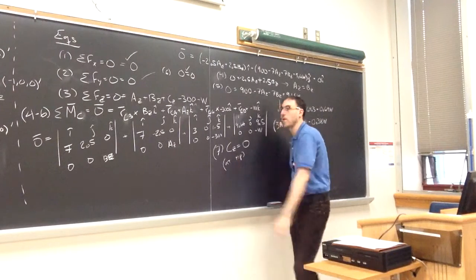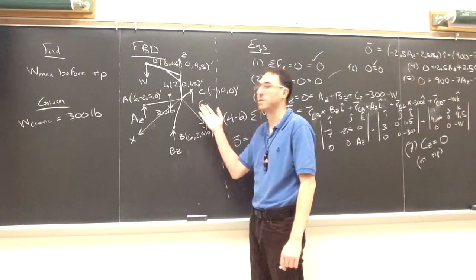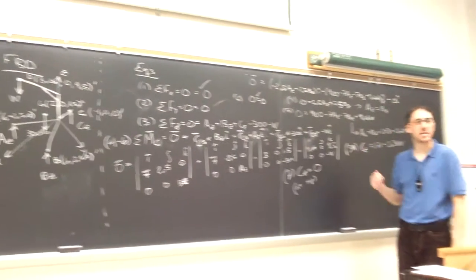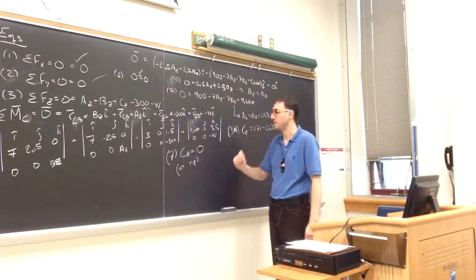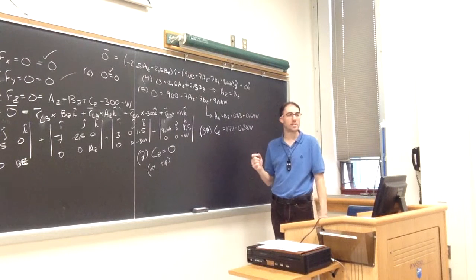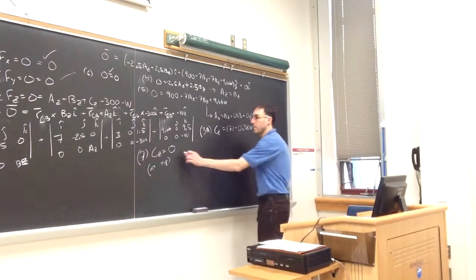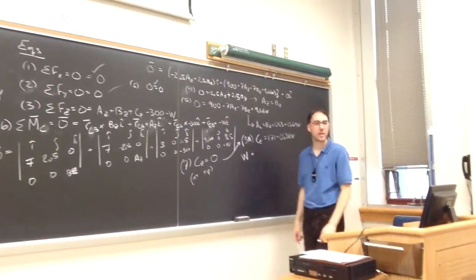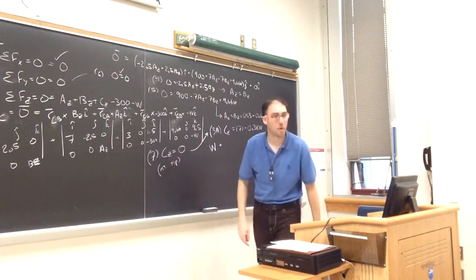Again, the free body diagram is true for equilibrium. This is going to be true. CZ is still here. It's the equation where we set CZ equal to 0, where we're saying it's on the verge of tipping. That normal force drops and drops and drops, and it's just at 0. Now if we look at equation 3a, when it's on the verge of tipping, the only thing we don't know is W. So if we put this equation 7 into 3a, this tells us that the weight that will cause the normal force just to go to 0 at C is going to be 450 pounds.